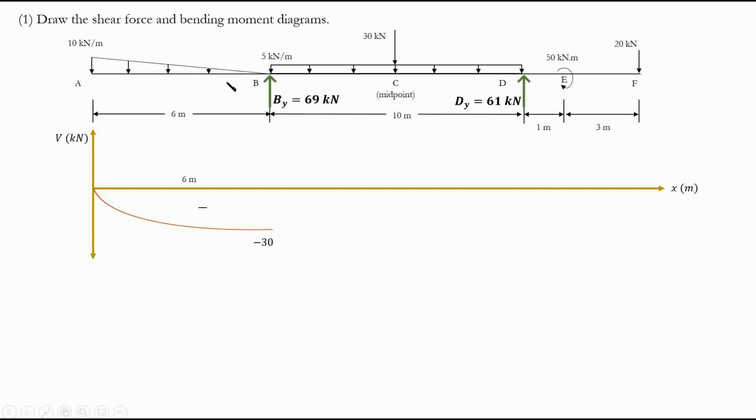But of course, the idea behind this is just integration, right? Because it has to do with sectioning, and of course you can find the proof. It's basically one of the basics of drawing a shear force and bending moment diagram. Of course, in some cases you might even have this as a parabola, right? And probably in your book, you can find examples representing a parabola, and the equation is even given, right? So the only thing we have to do is just integrate this one. If this equation is given, you just integrate that one, and draw this one, integrate this one, draw that one. Easy. That's the concept behind it. But for our purpose, the ones I mentioned are going to be enough.